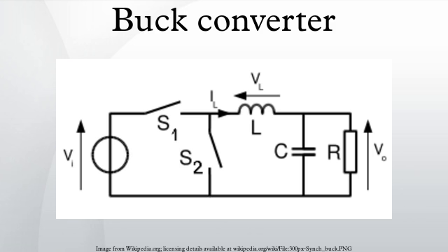For example, a MOSFET with very low RDSON might be selected for S2, providing power loss on switch 2 which is IO squared times RDSON times (1 - D). In both cases, power loss is strongly dependent on the duty cycle. Power loss on the freewheeling diode or lower switch will be proportional to its on time. Therefore, systems designed for low duty cycle operation will suffer from higher losses in the freewheeling diode or lower switch, and for such systems it is advantageous to consider a synchronous buck converter design.